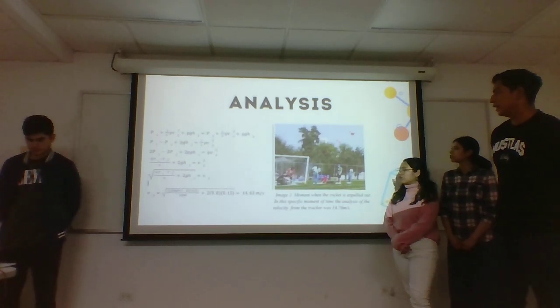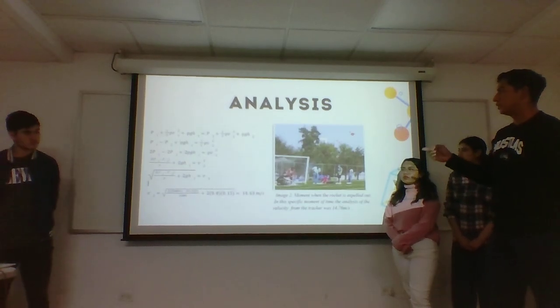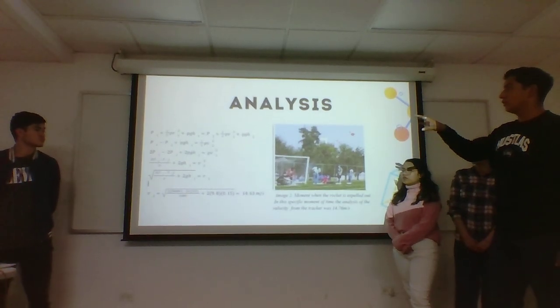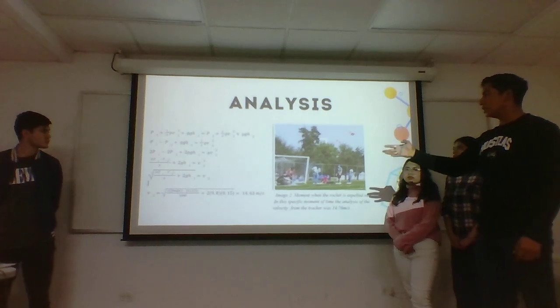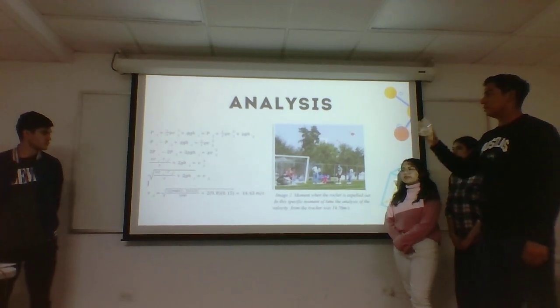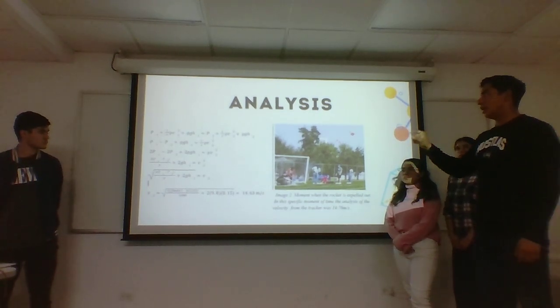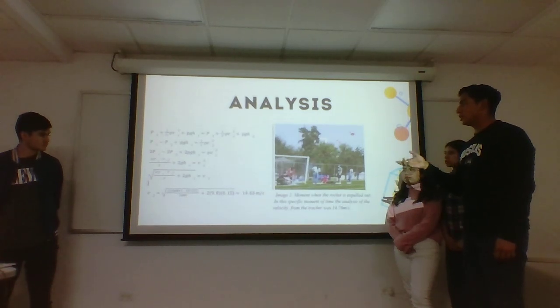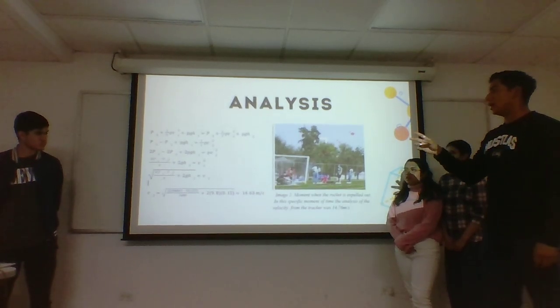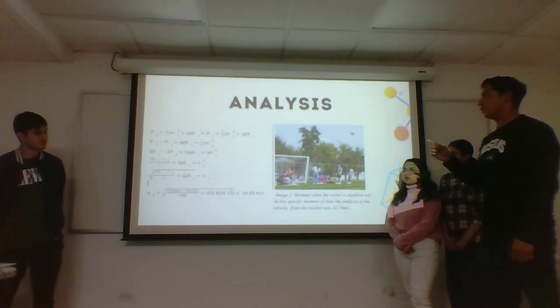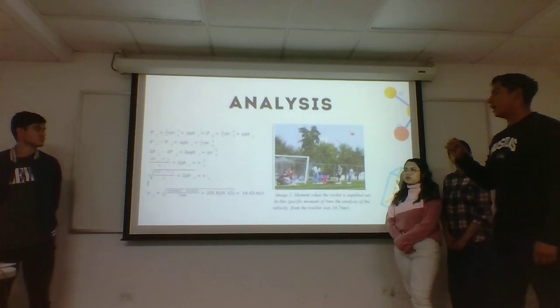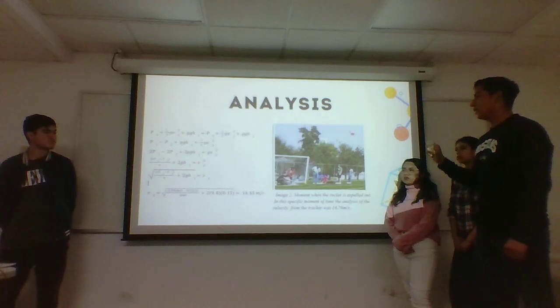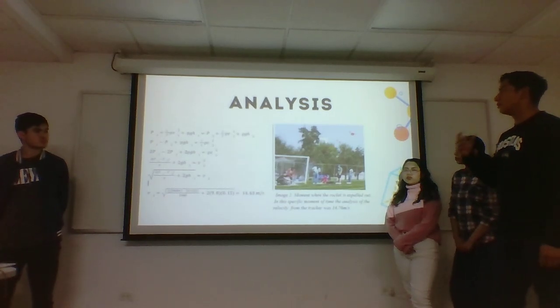First we got the velocity of the water expulsion. That was obtained by solving for the velocity in Bernoulli's equation, which gave us something similar to Torricelli's formula, using a pressure of 30 psi, the atmospheric pressure, and a difference of height of 15 centimeters.